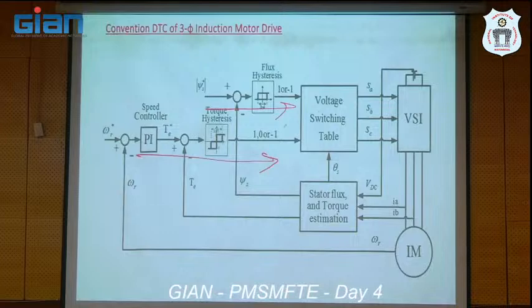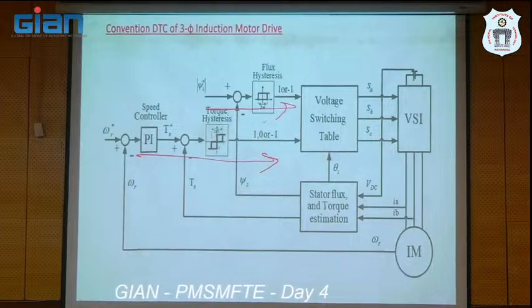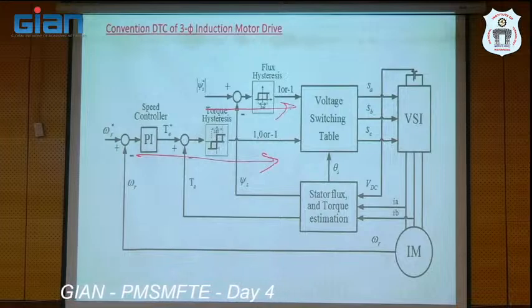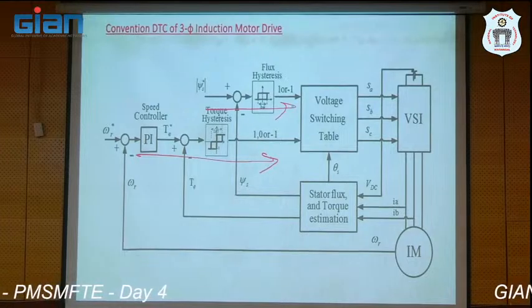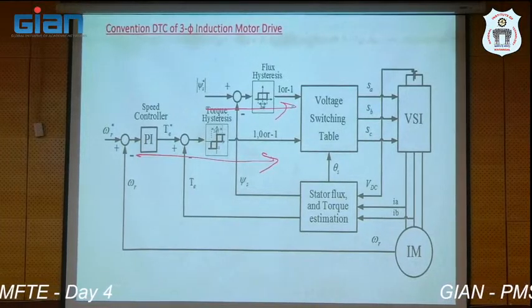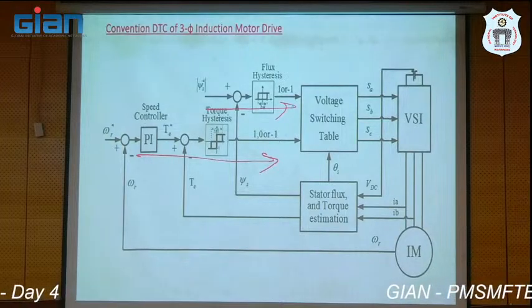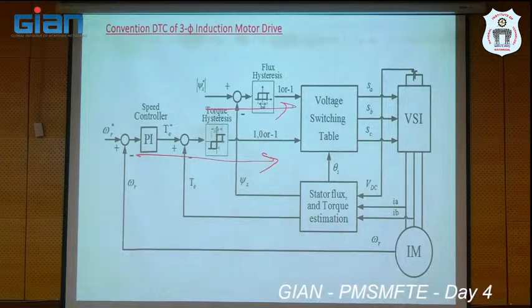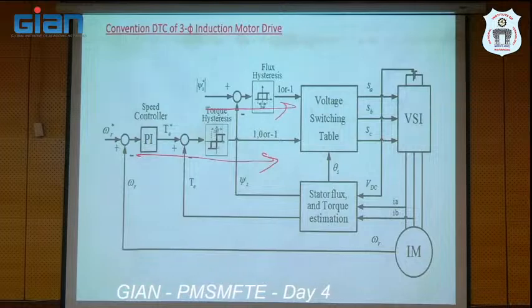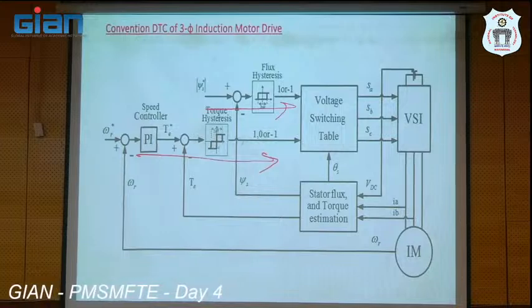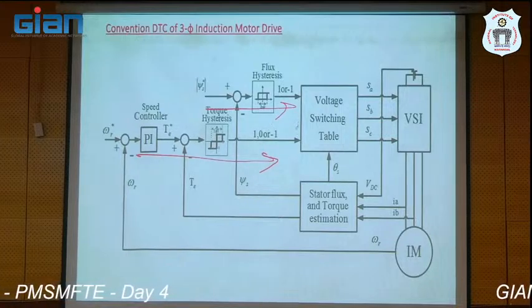One more important thing: if you take a hysteresis controller, the advantage is you need not bother about introducing an integral controller. You need not bother about delay in the response. A hysteresis controller will respond at each instant, but an integrator will not respond at each instant. You got my point? So at every sample period your hysteresis controller will produce the state 1, 0, -1.